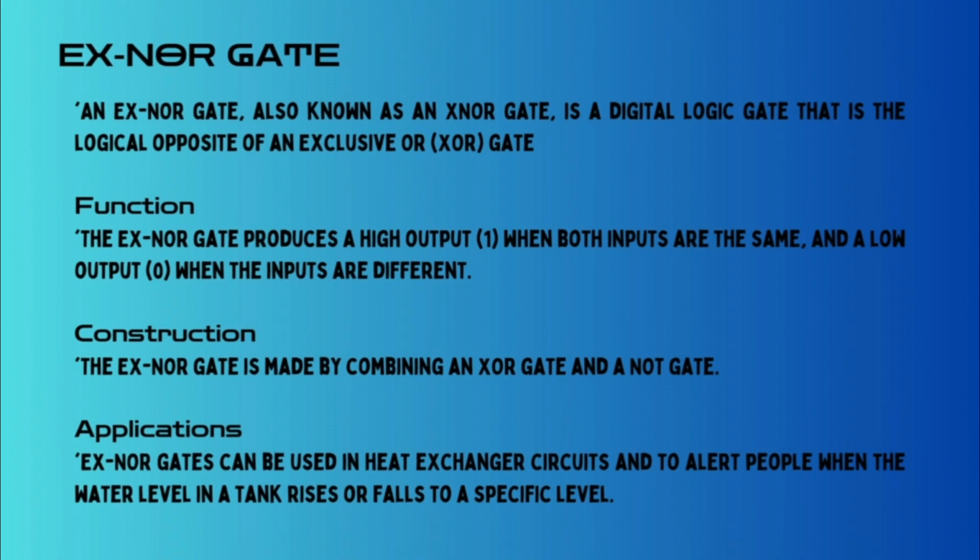Now, about the XNOR gate. An XNOR gate is a logic gate that outputs 1 when both of its inputs are the same, whether 0 or 1. In other words, it gives a 1 when both inputs are equal and a 0 when they are different. It's the inverse of an XOR gate, and it's commonly used in digital circuits for equality checking and parity functions. Together, System Verilog and logic gates like XNOR are essential tools in digital design and verification, enabling us to build and verify complex electronic systems efficiently.